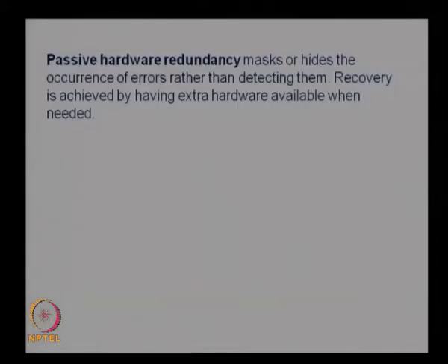The passive hardware redundancy actually masks or hides the occurrence of errors rather than detecting them. Recovery is achieved by having extra hardware available when needed. So, here in the passive hardware redundancy, it will not really detect the error, it will basically mask the error. Whenever there is an error occurring, the system will automatically mask that error or hide that error and function as if nothing has happened, or as if there is no error in the system.